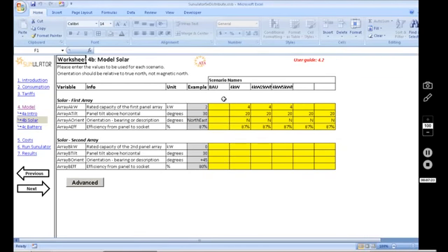That's perfectly valid. But you can imagine if you had a roof that was one side was facing east and one side was facing west, for example, then you'd want to enter those two sections independently. If you've got a more complex roof which has 3 surfaces all facing different directions or more, then you can't model it explicitly in Sunulator.